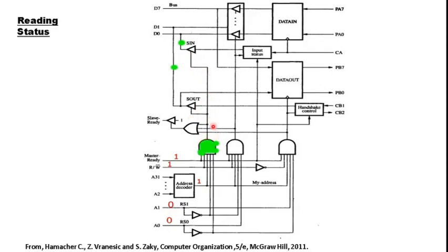If you see, these control lines go to this AND gate marked in green. So the activation of these status bits, or status register contents, depends on the activation of this AND gate. We need to know when this AND gate can be triggered. Obviously we know the master ready signal is necessary for this entire interface to function, as it is wired to all the components. Then as our operation is a read operation, in the read write section we should give a 1.